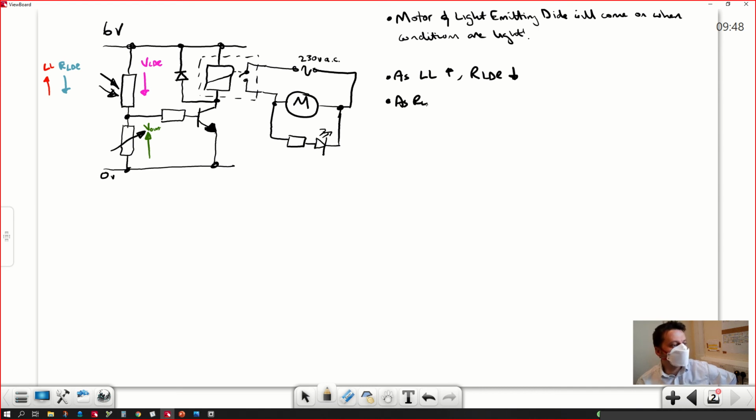As the resistance of the LDR goes down, the voltage across the LDR also goes down. As the voltage across the LDR goes down, V out of the sensor must in this case be going up. So that description of the input sensor essentially describes the operation of that thing as a light sensor. When light level is high, V out is high. It's a light sensor. You then move on to describe that kind of switching process.